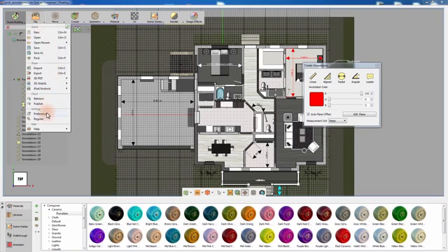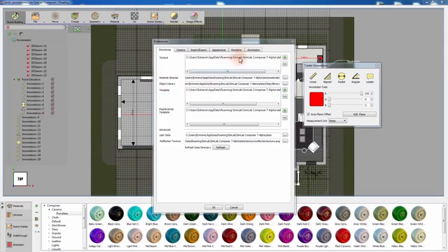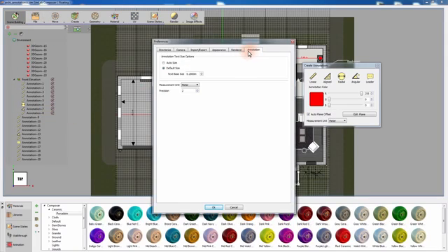Additional attributes for the annotations can be accessed from the Preference window in the File menu. You can find an auto size option which will determine the size of the annotations automatically based on the size of your model. You can change the measurement unit and also set the annotation precision, which controls the number of decimal digits to calculate in the annotations.